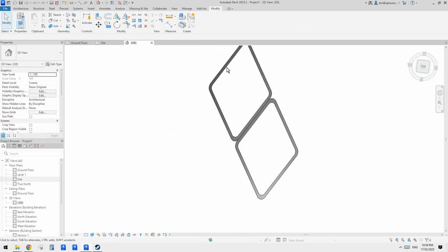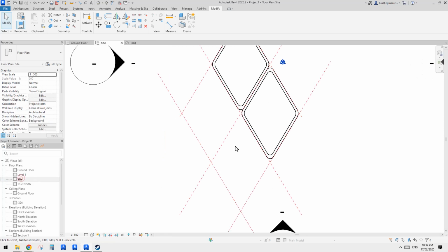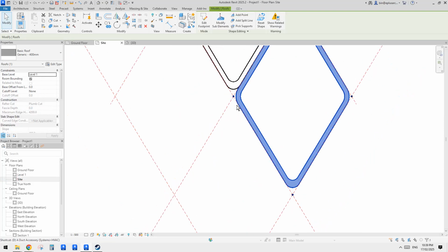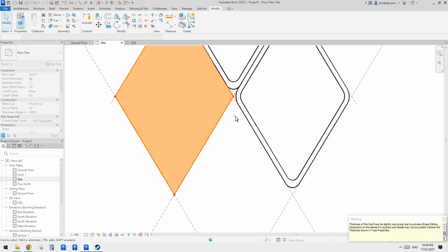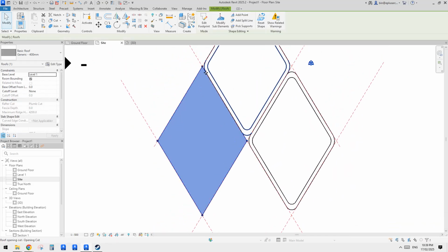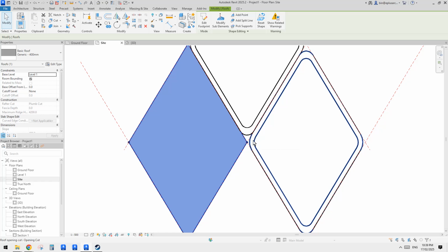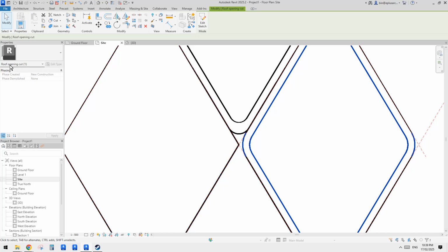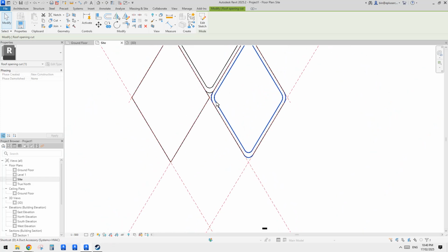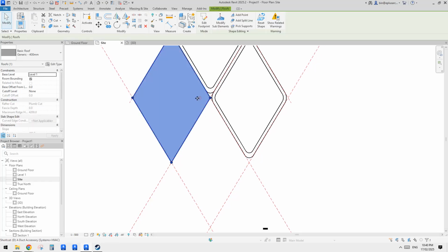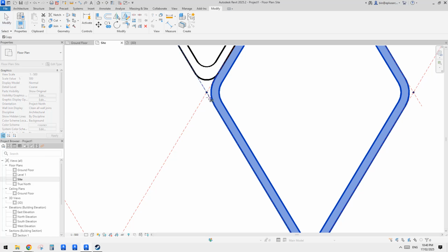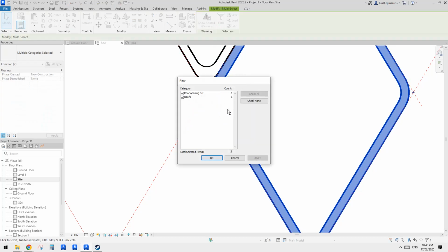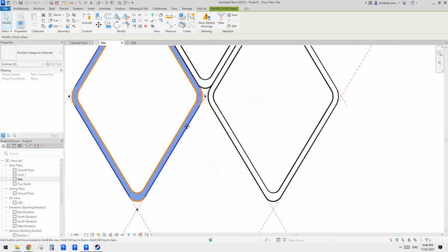Okay, so now let's have a look, actually go to side plan again. If you only select the roof and then mirror it, I'll just do DM, you won't copy the opening. So which means you need to do the opening. I'll try to only mirror the opening. I'll just try to do the DM. Doesn't work. See? So if you want to mirror the whole thing, you need to select both the roof and the opening. Okay, so DM mirror, and then we have this.